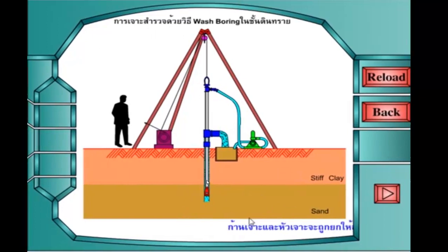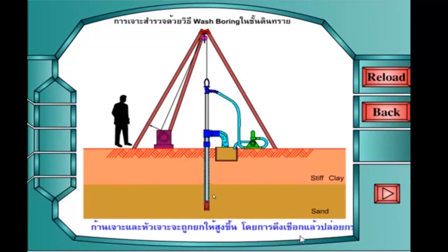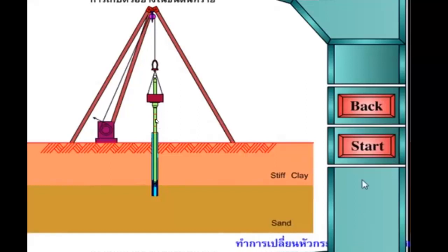Okay, so they first take one data point on this sample, and they are going down. Suppose they take data at around 5 meters, so now they will take another data point at maybe 7.5 meters. So they are making a borehole, and they will go to the desired depth. Okay, and after that they remove this, and then they insert the sampler. Can you see the 3 markings? They insert the sampler.